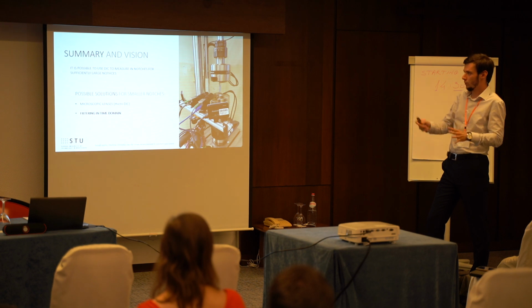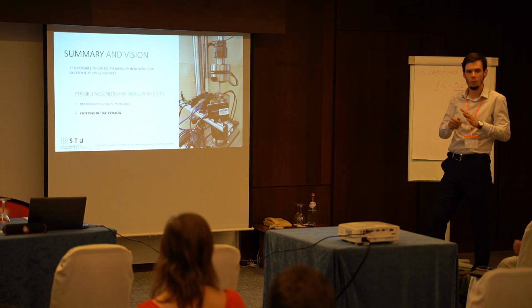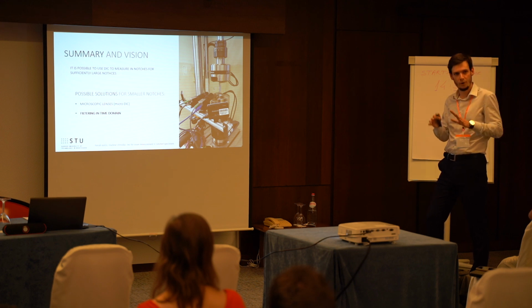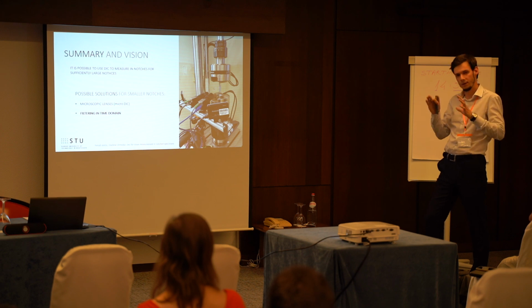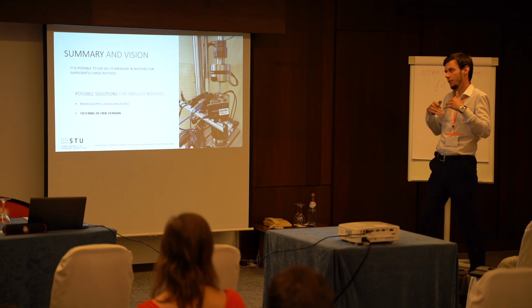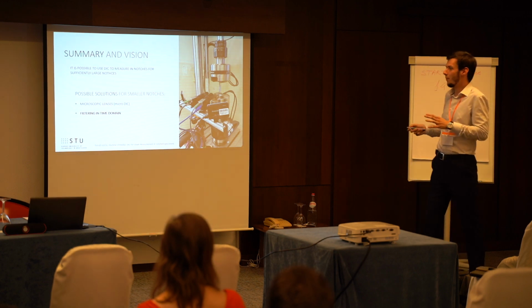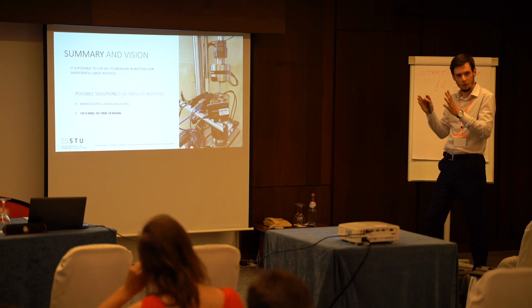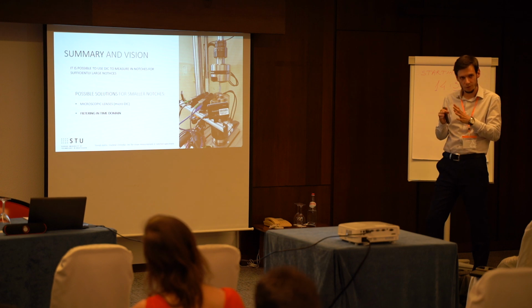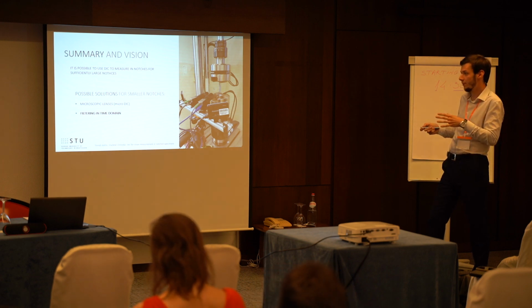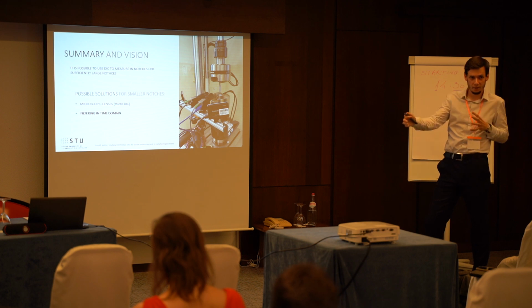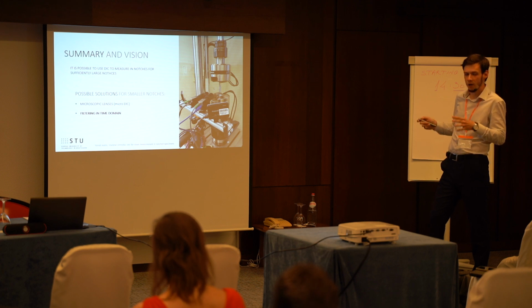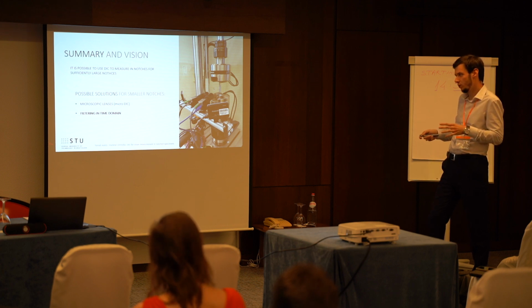So let me summarize what I've been talking about. We consider digital image correlation a quite well suitable method for measurement in notch specimens and sharp notch specimens as well. But the notch has to be sufficiently large in the picture. Possible solutions for smaller notches are, for example, microscopic lenses or some kind of change of the measurement equipment, or the thing I'm working on currently, and that's filtering in the time domain as well.